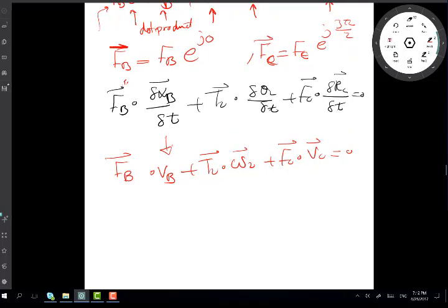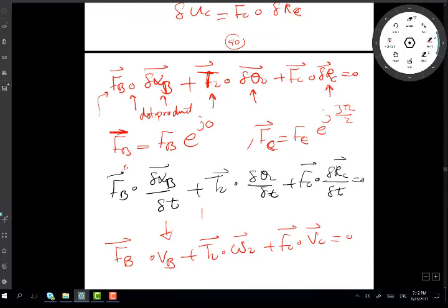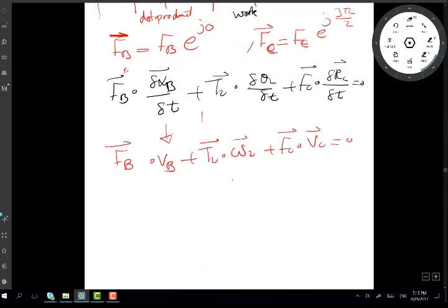So this is a small transformation of the equation by just dividing by delta T. So we move from the work, Newton meter, domain to the power domain. So this equation is more of a power equation. I was talking before about here, this was more like work. This was really a work equation. Now this equation is more like a power equation. It is the same equation, just dividing the displacements by delta t. I get a power equation because we are more used to omega and velocity terms and so on.